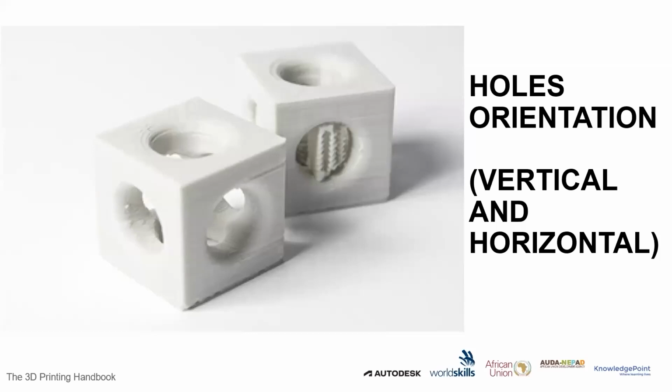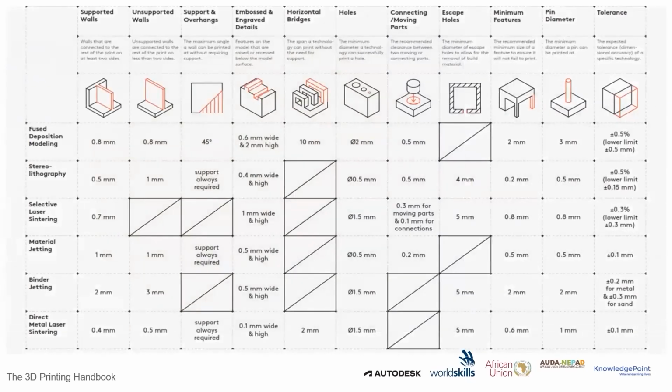But in here, it's important to remember that you need to give a little bit of clearance because of the adhesion and the oval shape that is being created. When a print comes in here, there's an offshoot around that oval shape instead of a circular shape. So you may want to give a little bit of clearance of about 0.1, 0.2 in your design, to accommodate the oval shape that was not put in place, from the theoretical extruding to the actual extruding. So it's very important, and this is something we really want to pay attention to.